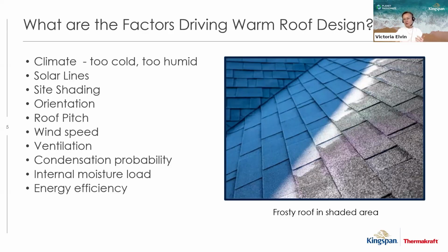If you remember, a cold roof design is where the structure is outside of the insulated envelope, and they can get moisture within them that needs to be dried out by returning it back into a gaseous state so the ventilation pathway can take it out.